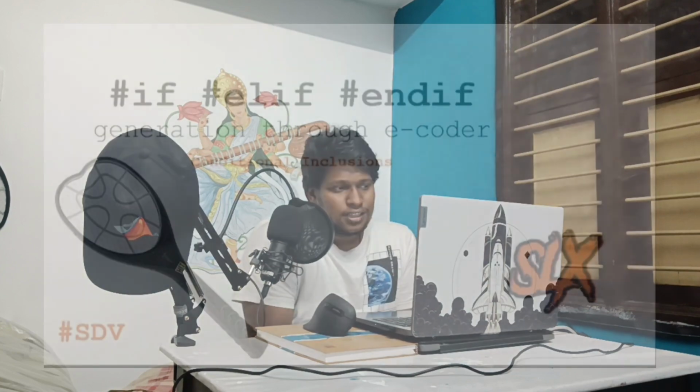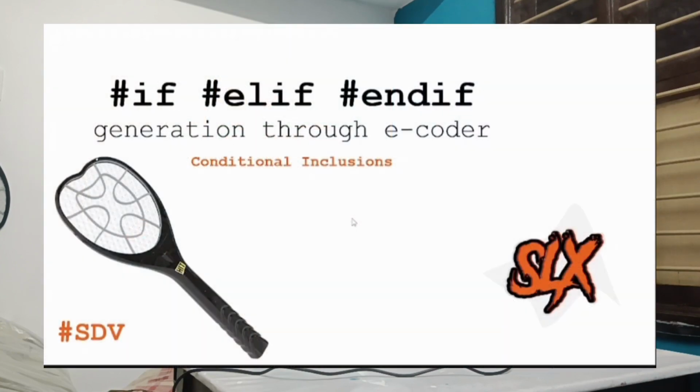Today we are going to see code generation through Embedded Coder. Here I have some things for you: #if, #elif, and #endif. What about conditional inclusions? Most of the time we use them to generate code through Embedded Coder and AUTOSAR Coder. Today we are going to generate #if, #elif, #endif, those conditional inclusions, through MATLAB.